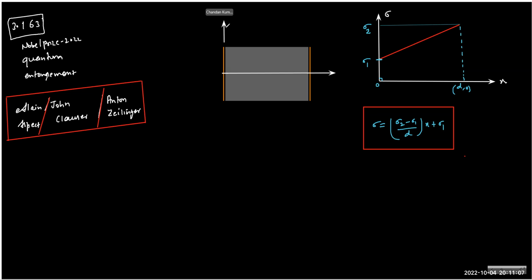That's it. Anyway, so once we have sigma, and we know it's varying along the x-axis, because sigma is varying over x, if you move x and cut a dx, then across this dx we can say that the sigma will not change, because this is so small that sigma at this location up to this location is almost the same.